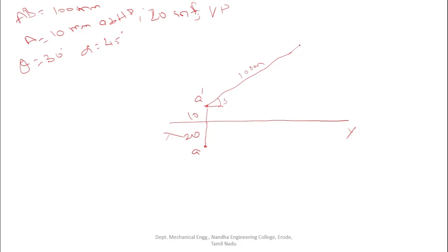Okay. So here the theta will fix the distance between the other end of the point from HP. So the theta is responsible to fix the distance between the point B and HP. So this is the B1 dash. B1 dash is influenced by this 30 degree, that is the theta. So from here draw a horizontal line. This is the locus of B dash.